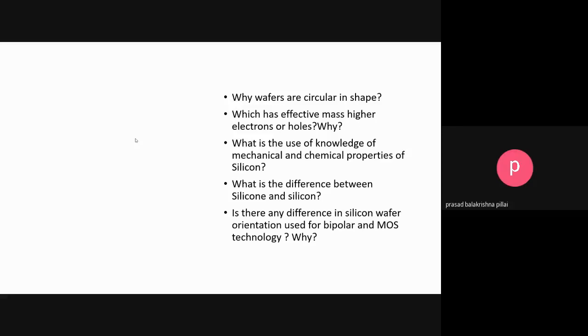That is a surface state actually. What happens is they can capture the carriers, so they will cause leakage current, etc. They can absorb, I mean capture, the carriers or atoms from the surroundings, and all those things happen. So the immediate problem is of surface state. We will discuss that in more detail later on when we discuss the surface state and things like that.